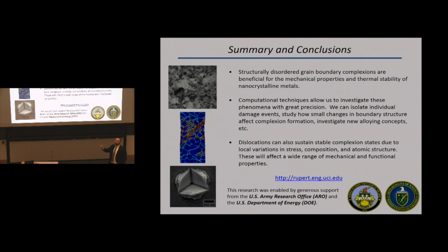I can imagine also going the other way. If you know you have a certain type of interface inside of your alloy, and you could go and get a reasonable amount of characterization, you can then study how that type of interface responds. When I do a TEM sample, I can find the structure of an interface, but I don't know how that individual interface will respond. It's almost impossible to test that. I know how the aggregate of my sample responds. So I could use that to choose what I model, or use that to choose what I make. Those are, to me, the most obvious directions of having these things work together. And often the choice becomes, what's the unknown? What's the bigger problem you have at the moment?